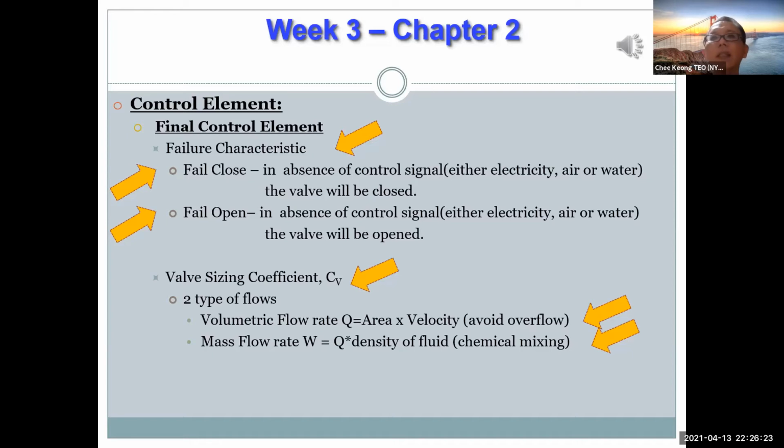For water, the case is different. When it freezes to ice, it will expand. And when it expands, what will happen to your valve? If you design just the nice size, it will crack and burst. So in order for this not to happen, you need to size the valve properly. And of course, for other considerations later, you will realize that we put in some extra measures to make sure that the valve does not burst.